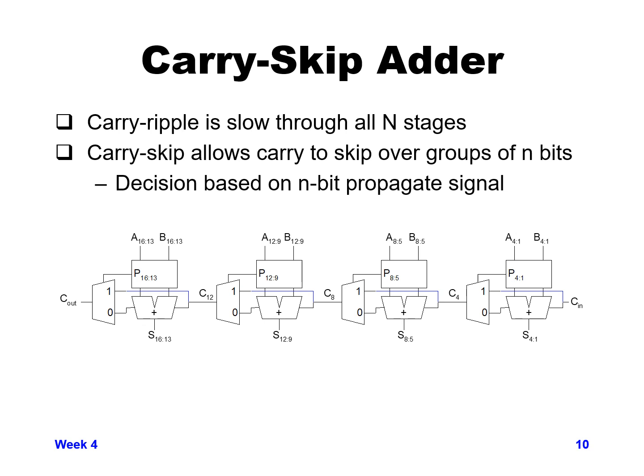Now, when we have our Cin come in from the very right hand side, we've calculated propagate 4 through 1. Based on Cin, we can determine whether C out goes out to C of bit 4, and now C sub 4 just goes through a single delay to be compared with the value of propagate 8 through 5.